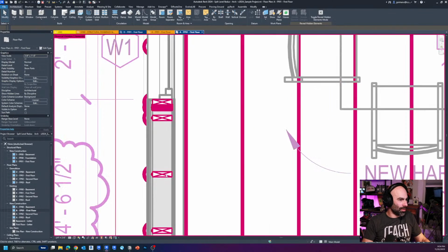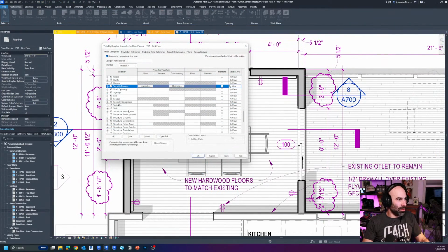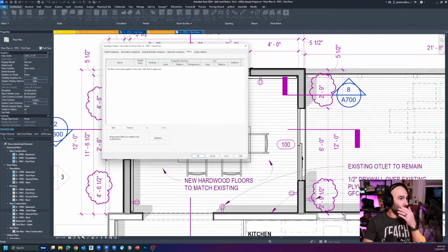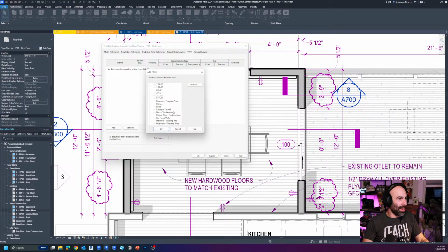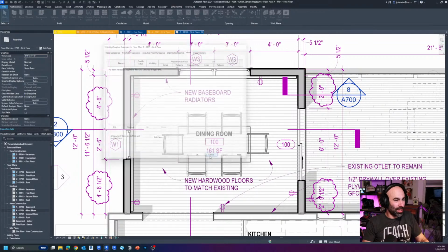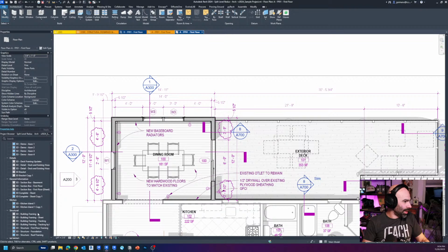For structural elements, for example, that kind of stuff, most of it you can filter out by categories, right? If you wanted to, then I would use filters. Notice in here I have interesting filters when I go in here. I have ones by date. I was tracking install. And then I have things called battens, boards, concrete takeoff, not pressure treated.